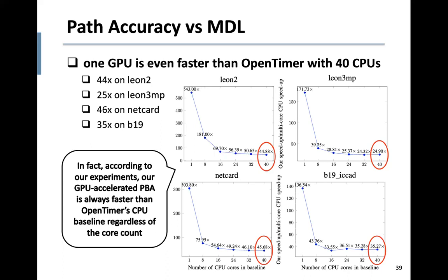I think one of the key differences between GBA and PBA is the data size, because when you run GBA, you do not have too much data compared to PBA. In PBA, for example, we request, let's say, 1 million paths, and you need to analyze a huge amount of data across those 1 million paths. But in GBA, we only consider a linear graph-based update, so we do not have too much data. That's why on GPU we don't see this significant benefit, but it still runs faster. It's still much faster than CPU. Sure, so the CPU version maybe benefits from cache locality or something, and gets better runtime? Yes, that's true.